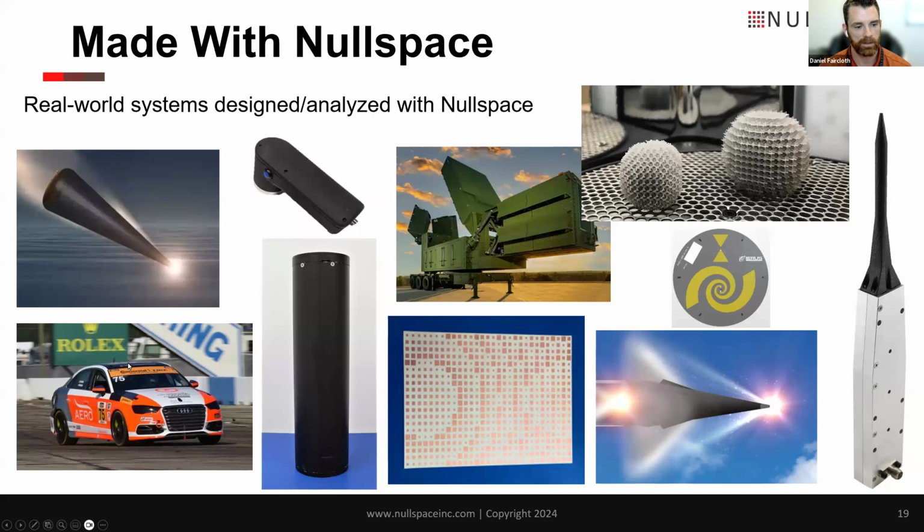So there's a voice comm antenna embedded into the paint applique on the roof of this car. The idea being, if I can get the antenna out of the windstream, it lowers the drag on the vehicle, improving fuel efficiency. It also opens up unobstructed space for better advertising. And so this was a very technologically challenging application. The antenna had to be very thin. It had to function over carbon fiber ground plane.